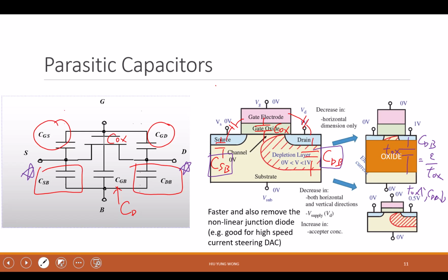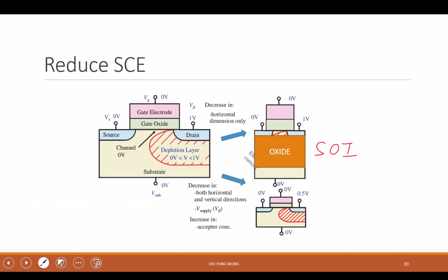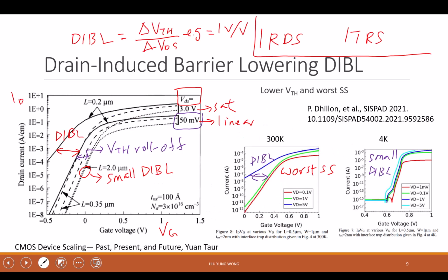Can we close the discussion from the last slide? I was just trying to understand the DIBL improvement at 4 Kelvin. Yeah, so basically what you're saying is this DIBL improvement at 4 Kelvin is not due to anything device physics-wise. It's just your subthreshold slope, subthreshold swing has gone up. And that's why all these curves kind of bundle together. And you don't see a big difference between linear mode and saturation mode operation. Did I get it right? Now, maybe I'm not complete.